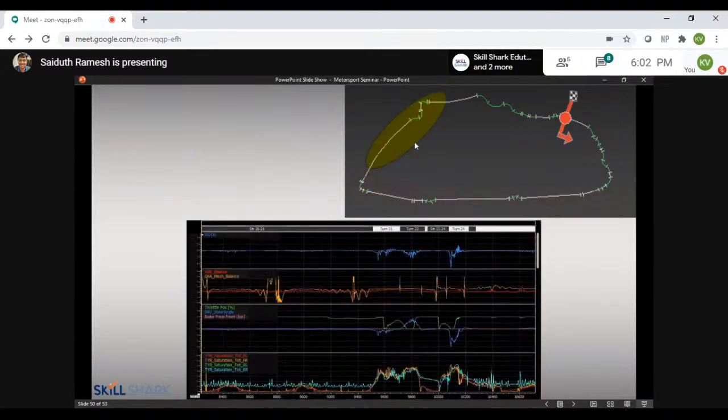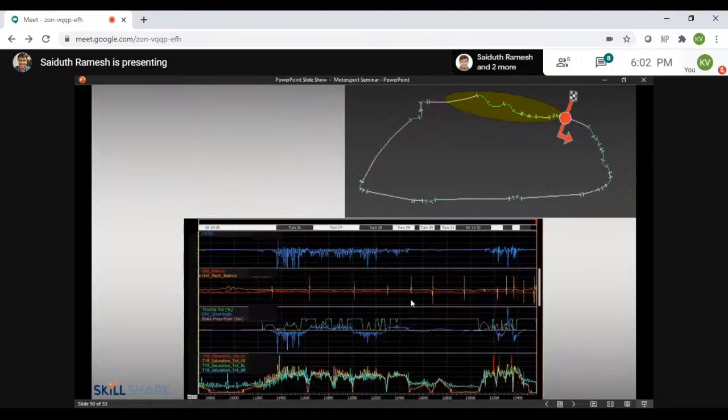This is kind of straightforward, nothing much to really see here. You see how the driver inputs the steering and the throttle as he goes through that section. You go through the final section, high speed Porsche curves. You see how much it's vibrating over here, and we actually set this up to be an understeering section. We set up the car to understeer through the section because it's a lot more stable.